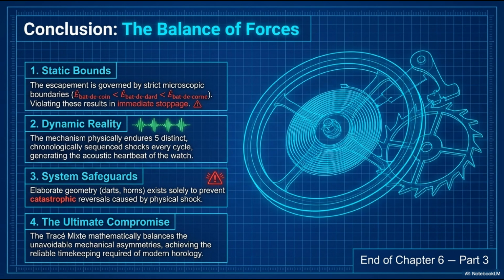The tick-tock sound is not incidental. It is the physical evidence of 5 mechanical collisions happening 8 times per second in a watch beating at 4 Hz. Third, system safeguards. The elaborate geometry of darts and horns exists solely to prevent catastrophic reversals caused by physical shock. Every millimeter of horn shape, every micrometer of dart length, is specifically engineered to maintain the safety hierarchy under